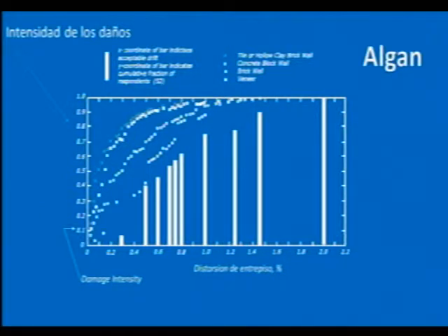By the time you went to a drift ratio of 1%, you had really lost all of the value of the attachments, if they were attached to the walls. So this worrying about whether steel or reinforced concrete will take 2% drift is a waste of time. You don't want to go that way if you want to protect the bankers.